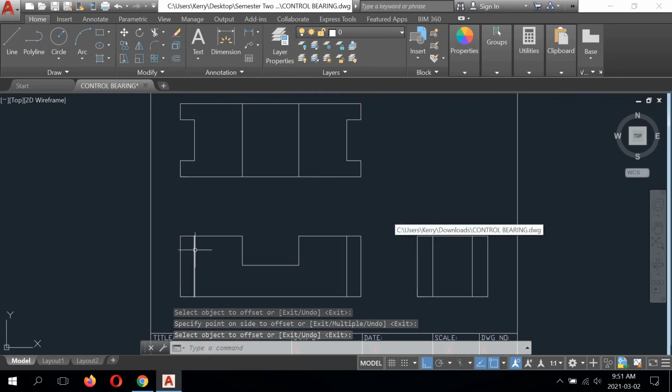Now we have to change the way these lines look, because anything hidden from our view cannot be white. Basically, the white lines are the darkest lines on a drawing. They've got the heaviest contrast and basically show the outline of the part that needs to be manufactured. It was the same in the single view drawings, but we didn't have hidden detail lines in those drawings because they were just single view drawings.